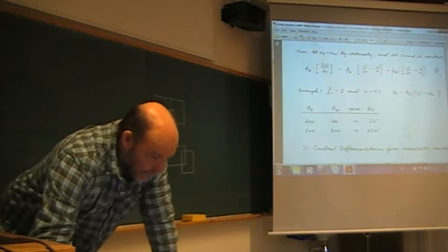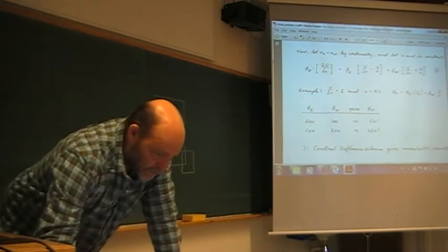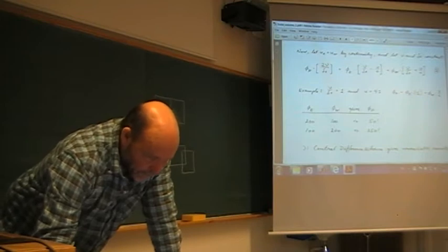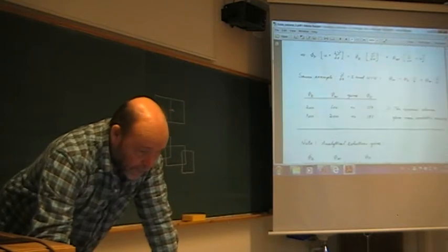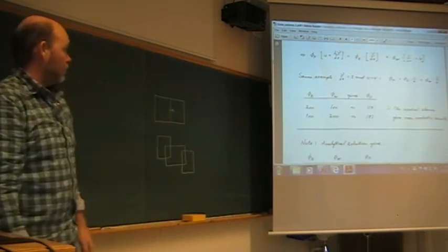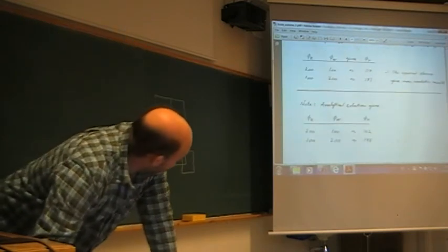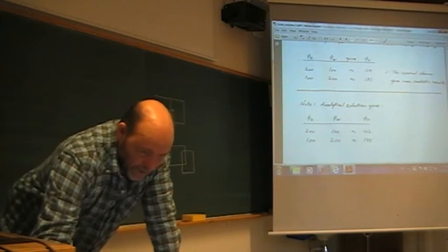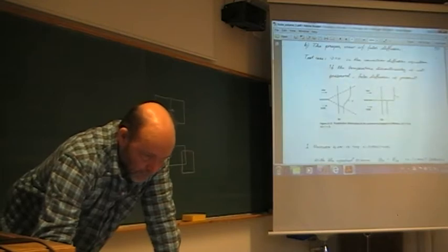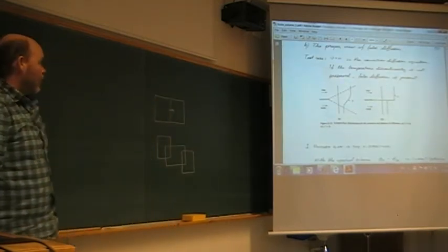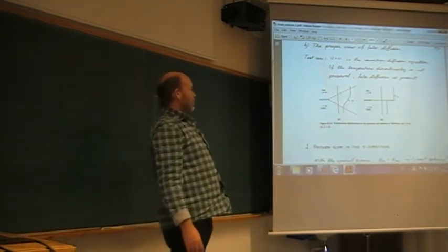So here, yesterday we saw this advection diffusion equation using central schemes blows up. So the remedy was the first order upwind scheme, according to Patankar, which at least gives you more realistic results, although pretty far from what they should have been, since it's only first order, and also we know that scheme is very diffusive. Here, taken from Patankar, the way he defines false diffusion.